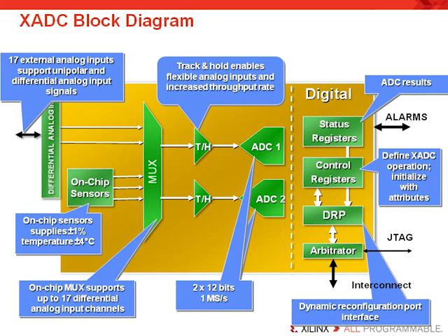The XADC core includes a separate track and hold associated with each A to D converter, which enables much higher throughput rate. The function of the track and hold circuit is to sample the analog front end and hold its voltage constant during the interval required for the ADC to perform the analog to digital conversion. The track and hold circuit performs sampling at much higher rate than the ADC, thereby improving the overall throughput. The track and hold also contains signal conditioning capability.